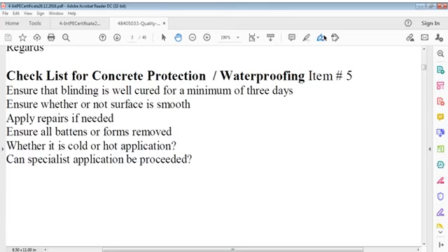So you are going to apply this waterproofing membrane, either cold application or hot application, torch application, or some other way, completely covering your vertical sides and horizontal portions and all foundations, whatever is there, and then starting your ground floor activity.